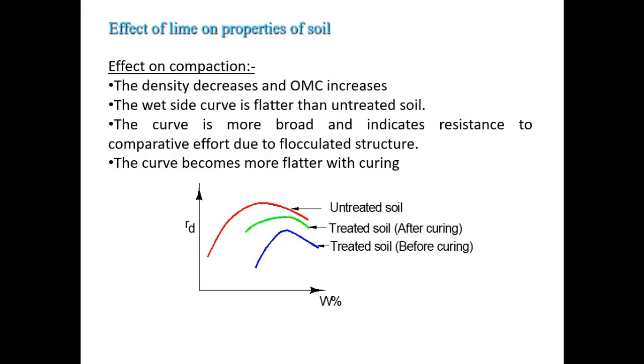The curve is broader and indicates resistance to compaction effort due to flocculated structure. The curve becomes more flatter with curing.